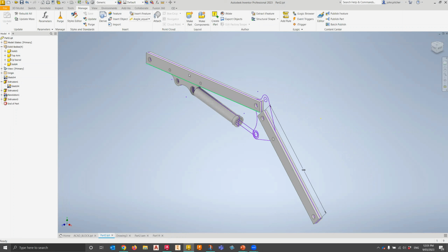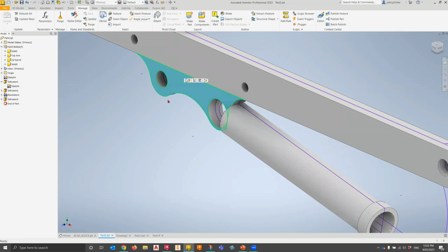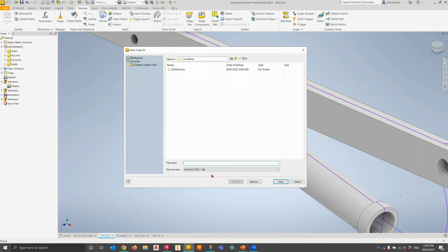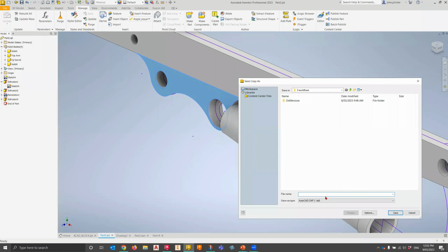and work with it there. One other little thing that I do find quite helpful inside of Inventor is we do have an option. For instance, if I wish to laser cut this particular component here, I can go in here and export this face by simply right-clicking. And for those of you that are familiar with the sheet metal space or working with laser cut and profile cut information, we can obviously export a profile directly from a face in Inventor as a DXF.